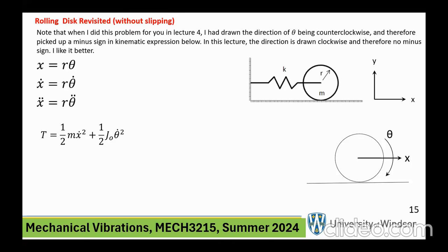Okay, so it's rolling. Now the kinetic energy is, first of all, this mass has a velocity that's moving in translation. So it's going to be 1/2 m v squared, but the velocity of this mass center is x dot. And then this is also rotating, for example, about the mass center. You can see that.